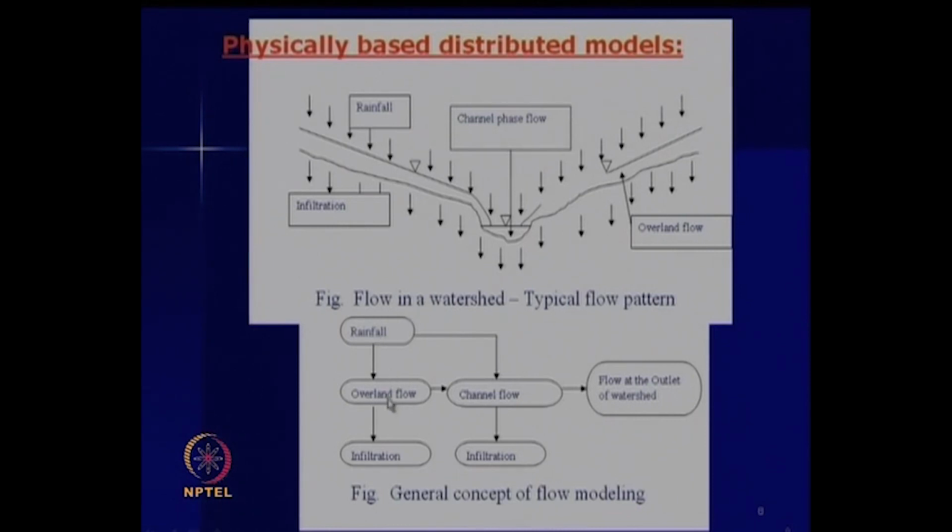So, the important processes like rainfall to runoff, the overland flow, channel flow components, and the infiltration parameters we can consider. This is the conceptual model which we have developed at IIT Bombay, by considering the overland flow, channel flow, and the infiltration modeling. Here this is an event based model. So, we have neglected the evapotranspiration aspects, since the rainfall is for a few hours and generally we will be simulating these kinds of events after a few rainfall seasons or a few events of rainfall.